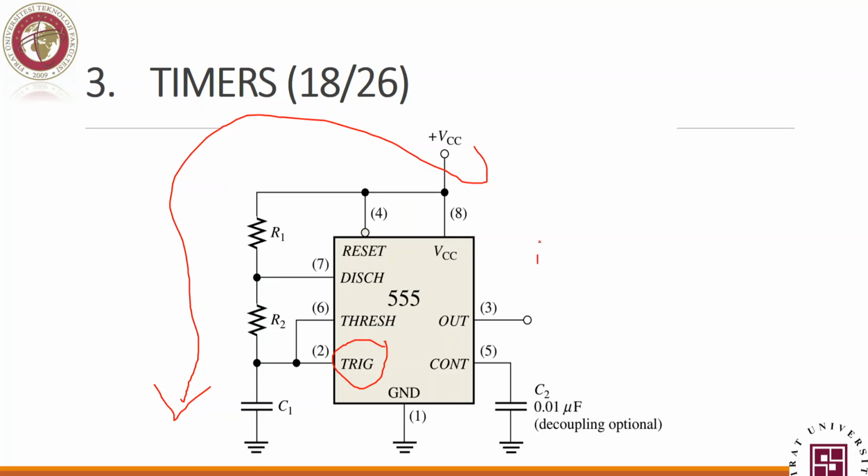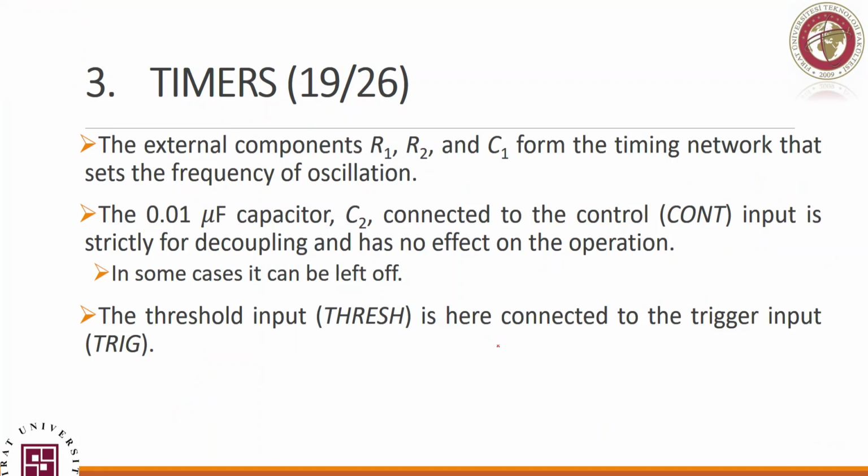So charge to 2/3 VCC, discharge to 1/3 VCC, charge, discharge, and so on, bouncing between states, and that will create exactly the output waveform. And usually this output waveform, as I said, is a square pulse. It's like the exact clock that we usually use in many applications.